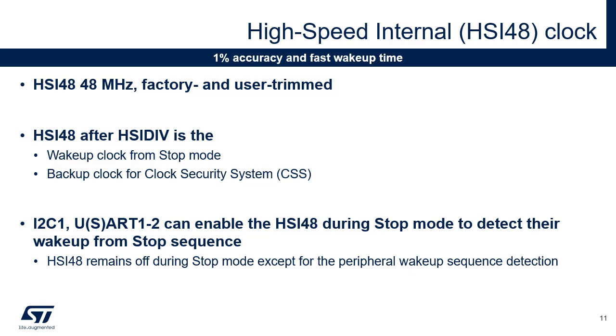The HSI48 automatically wakes up from stop mode to be available for peripherals that need it, even when it is not the system clock. Additionally, peripherals like USART1, USART2, and I2C1 can activate the HSI48 while the MCU is in stop mode if HSI48 is set as their clock source.